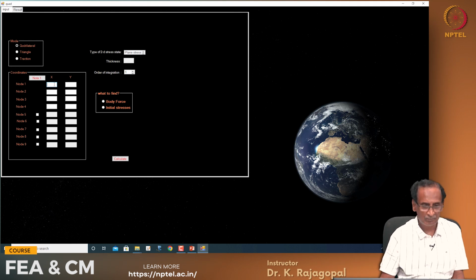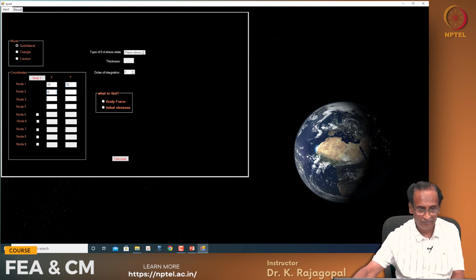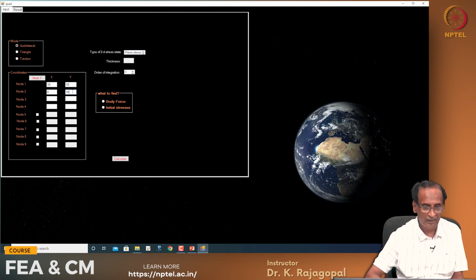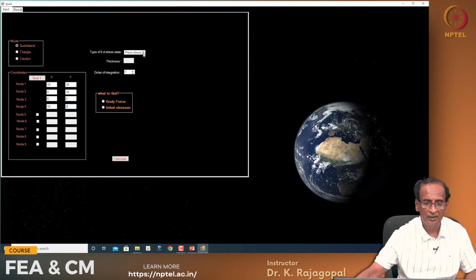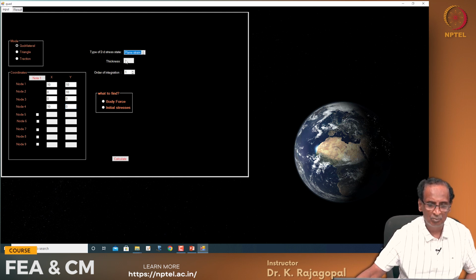Let's give some numbers. Let's say node 1 is at 10 and 10, node 2 has x as 0 and y as 10, node 3 is at the origin 0 and 0, and node 4 is at x of 10 and y of 0. Let's say we have a plane strain case and the thickness is automatically 1, and for the order of integration we select 2.